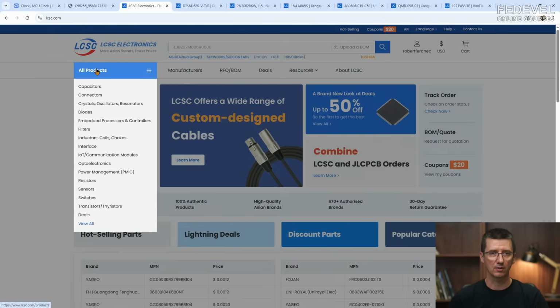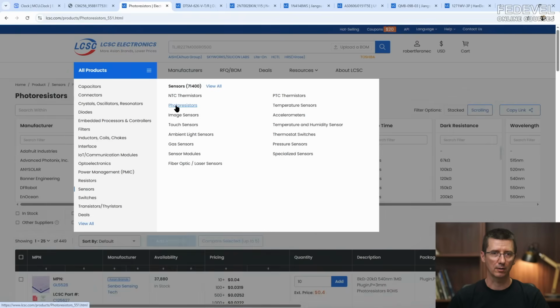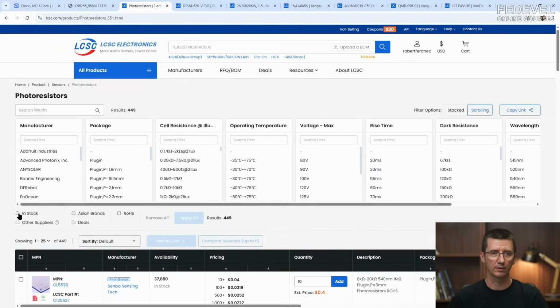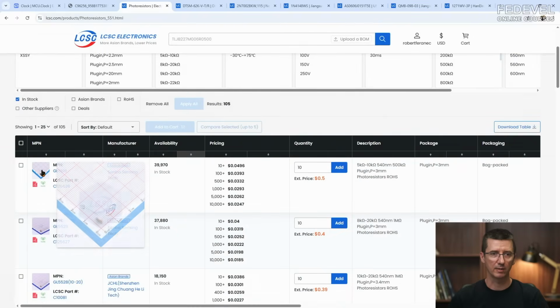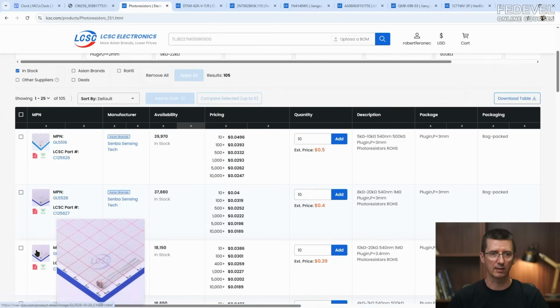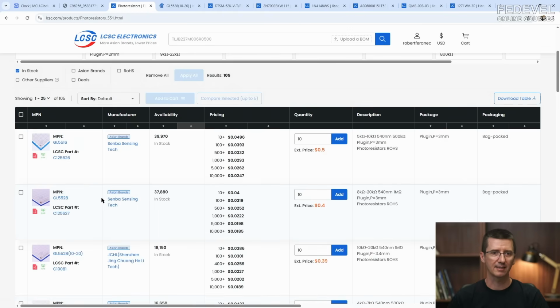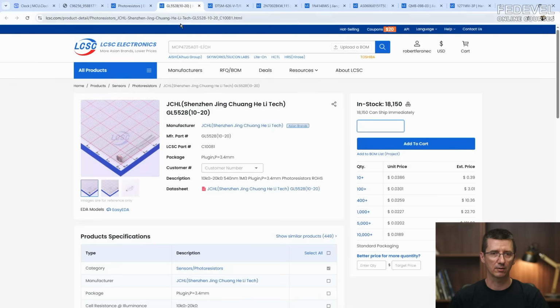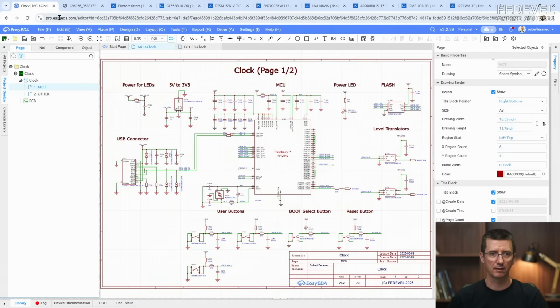Here we are going to put a light sensor, because we would like to control the brightness of the LEDs based on the ambient light. At night, the display will be a little bit dimmed. In direct sun, the display has to be very bright. We can use maybe something like this. Again, this is some kind of standard sensor, so if there is a problem to get it, you can always find a replacement.